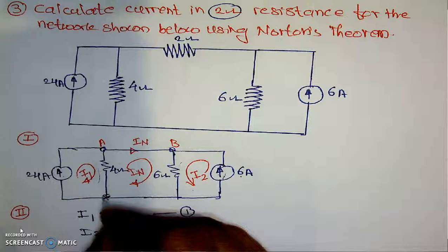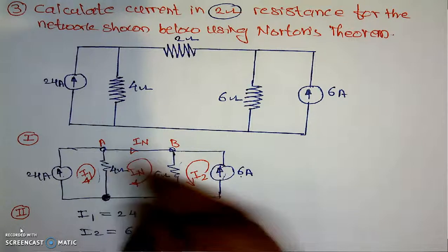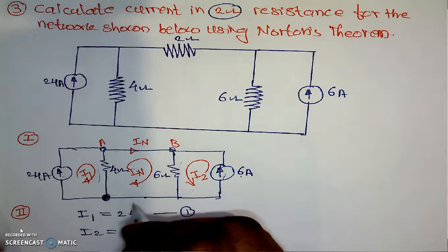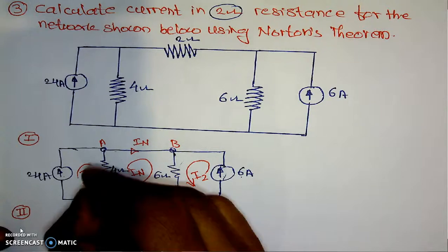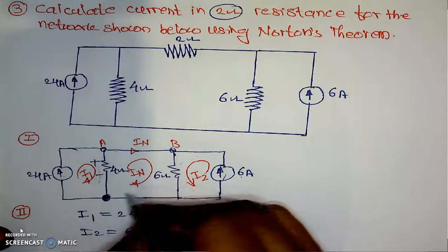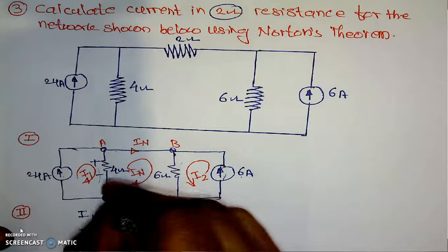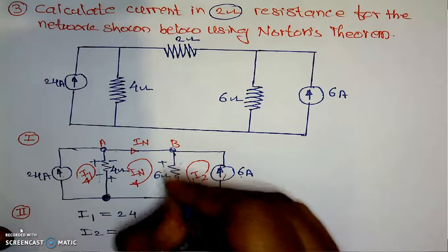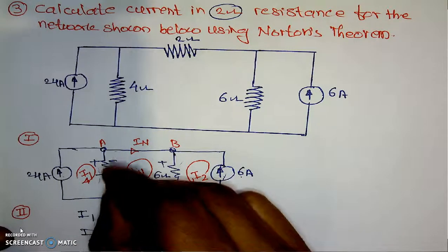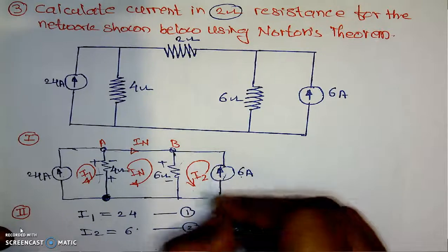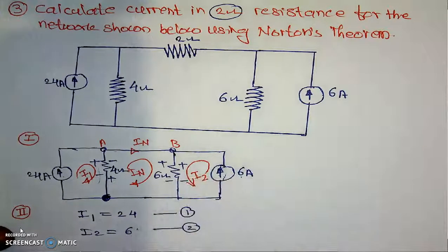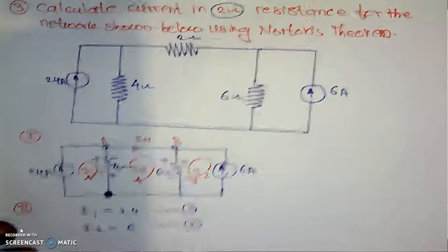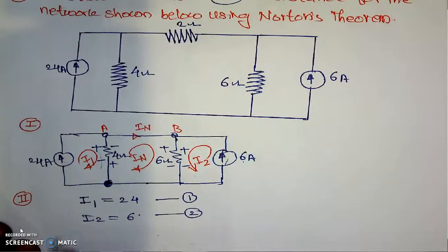For that purpose we are applying the KVL and we are traveling from this corner into the loop in the clockwise direction. Before that we will mark the terminals. This is clockwise current I1. This will be the plus minus. This is clockwise current again. Plus minus clockwise. Positive negative and so on. This is anti-clockwise. This will be the plus terminal. This is minus. And if we are applying the KVL to the loop number 2,